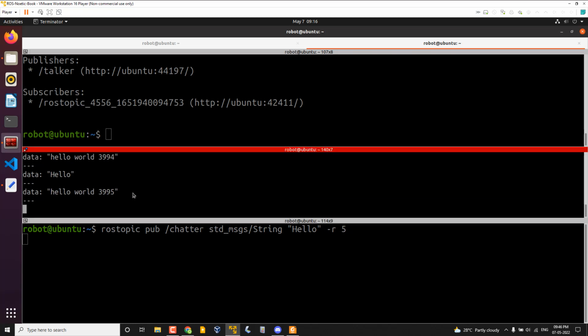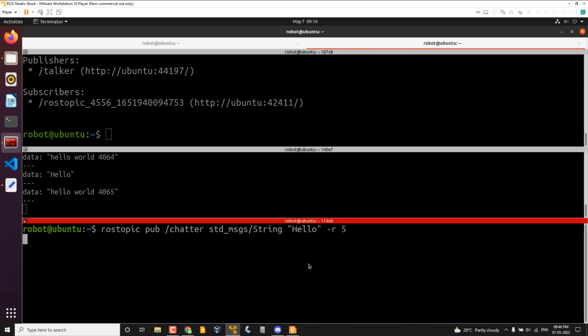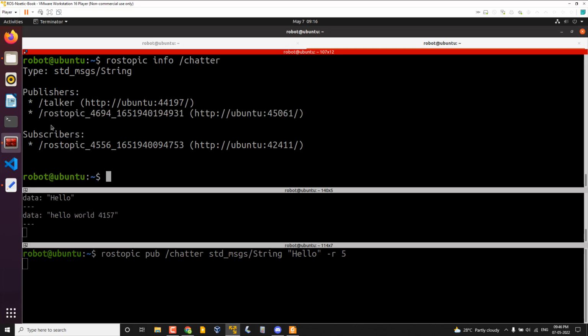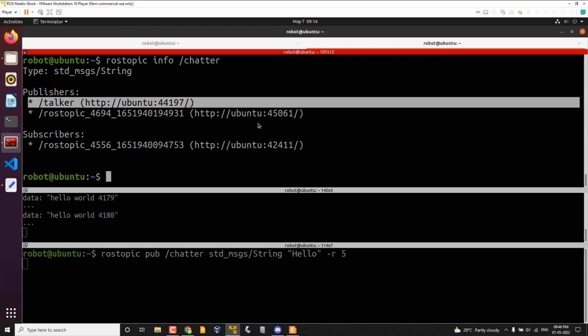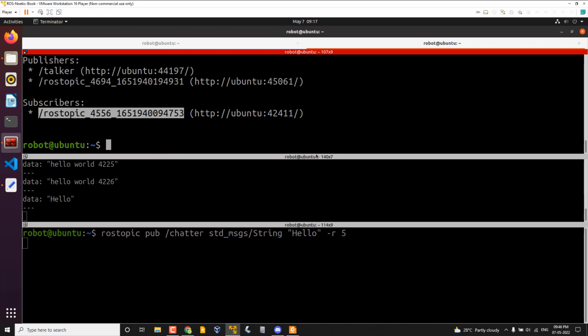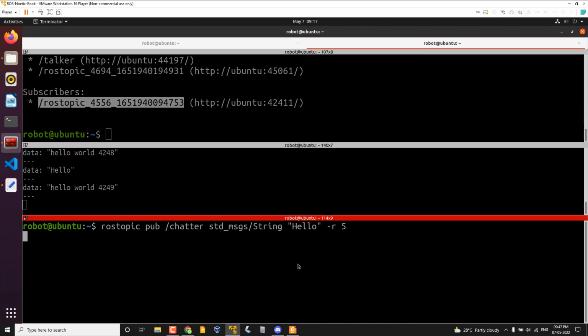Now you can see the topic is publishing hello world, and the hello that I'm publishing from rostopic. And if you do the info of this topic, you can see there are 2 publishers and 1 subscriber. Again, this is one useful command: rostopic pub, topic name, message type, then the data.